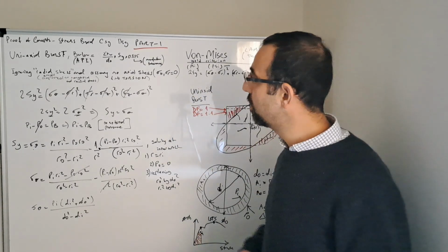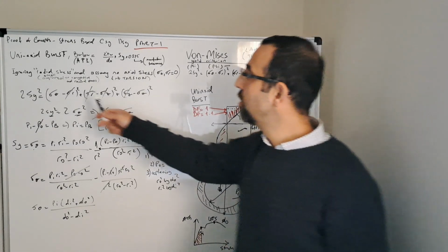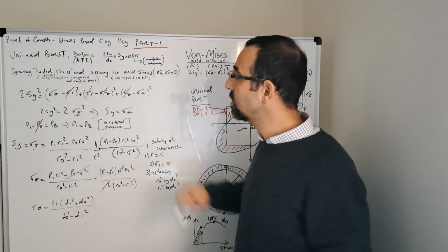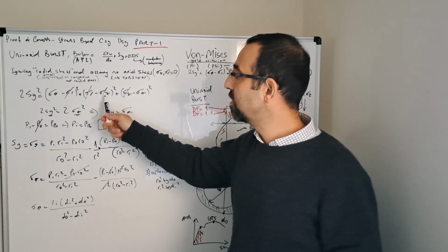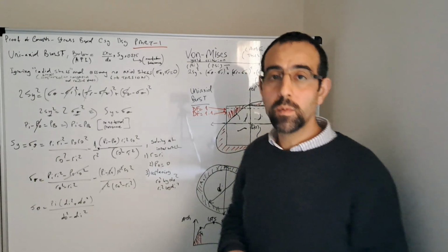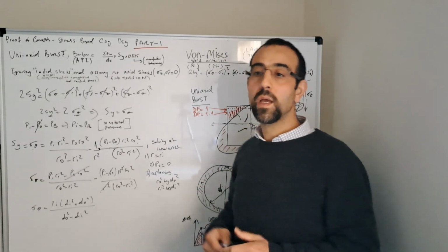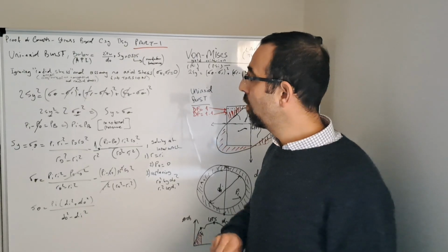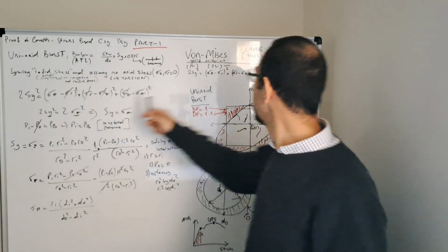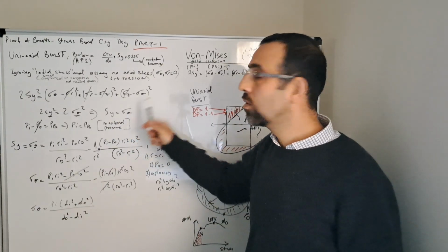We will use the von Mises yield criterion to come up with the Barlow equation. So we know that the Barlow equation is not accounting for the axial stress. So we count the axial stress as 0. Radial stress is usually negligible compared to tangential stress or the axial stress. Negligible because it's smaller usually. So when we cancel the axial stress and the radial stress, plus the torsion, we come up with the yield strength being equal to the tangential stress.